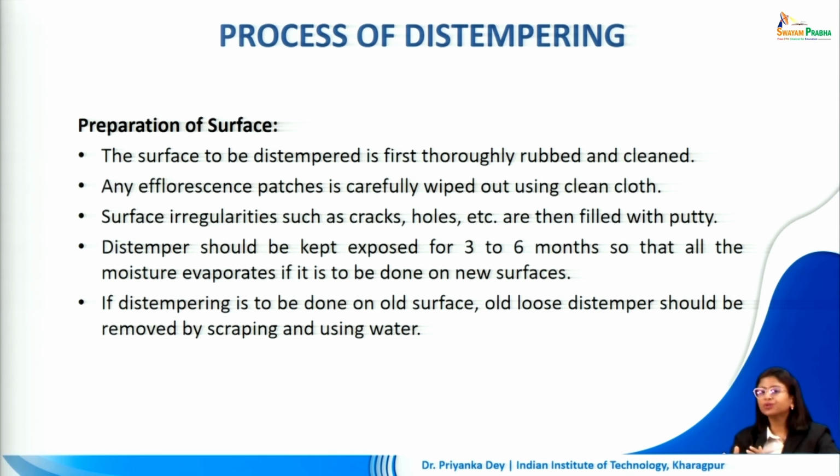The painting is not going to be able to alter the surface at all. It is just going to provide a decorative coating. So, whatever is the background surface texture will be very much visible even after painting. Only the opacity of the pigment is going to alter the color appearance and increase the durability, of course, of the surface. So, we need to use putty wherever there are any form of uneven edges or patches on the surface or background that we are dealing with.